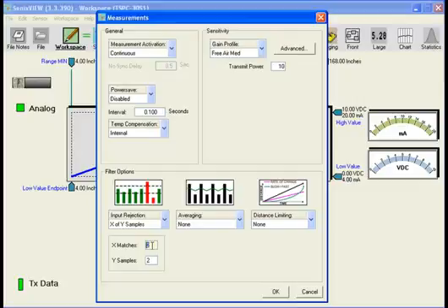And that eliminates any strange reflections or hiccups that you might have with the sensor, and sometimes ultrasonic transducers do tend to hiccup. Not often, but this will filter out any of that. I like to use it at 2 of 2, and usually it has no impact on what you're doing, except in some cases in tanks where it may.